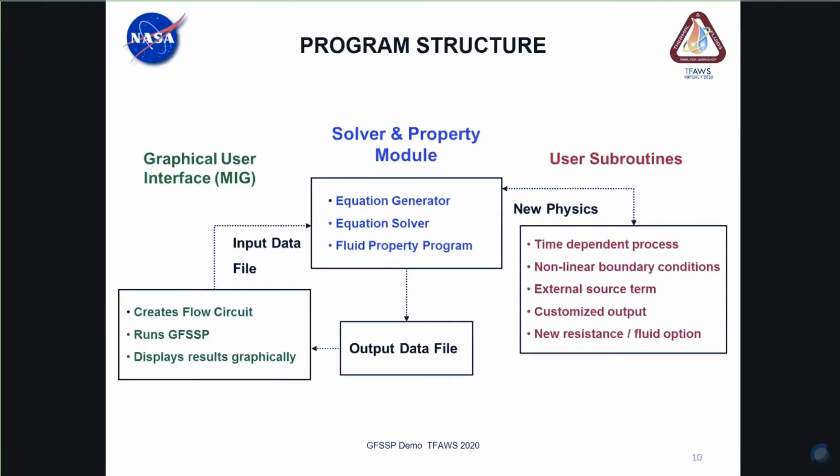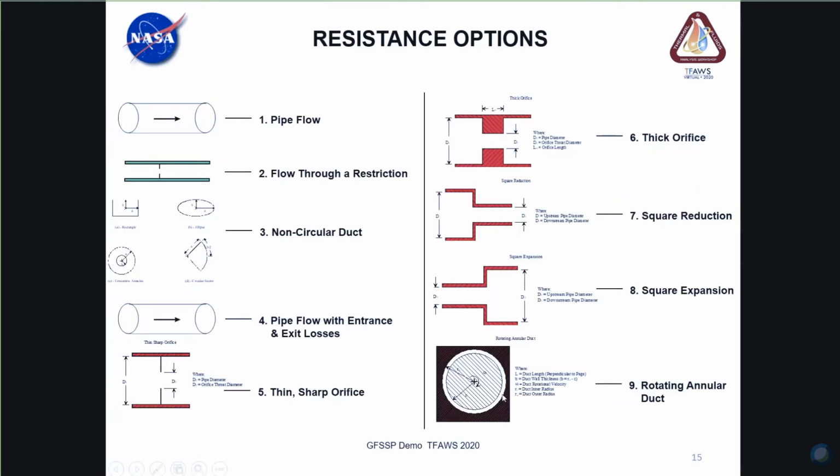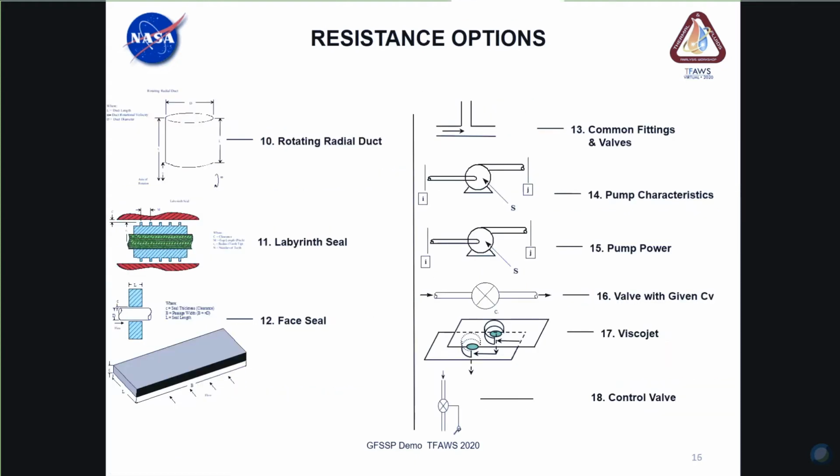So we do have for turbopump modeling various branches that model pressure drop in rotating parts. And there is also the possibility of, I assume what he's getting at here is the volumes of your nodes can change. Normally, nodes are constant volume.